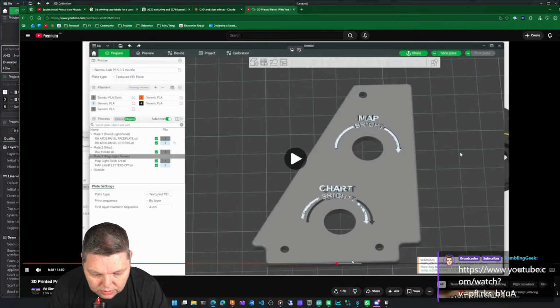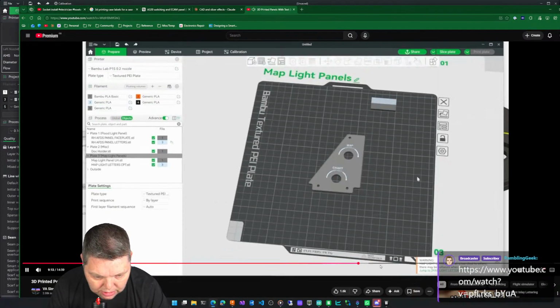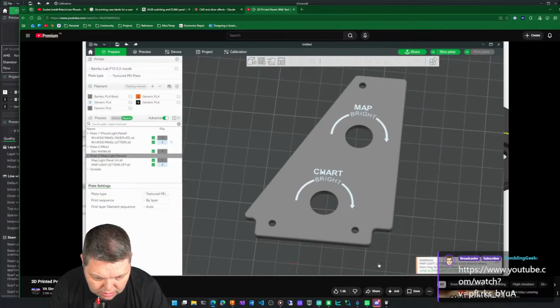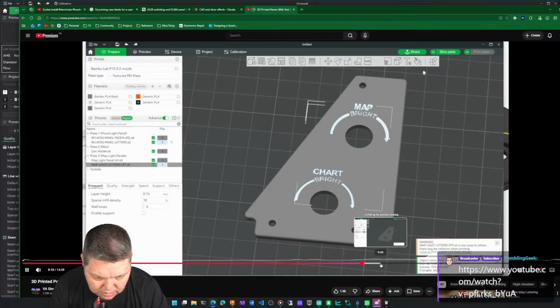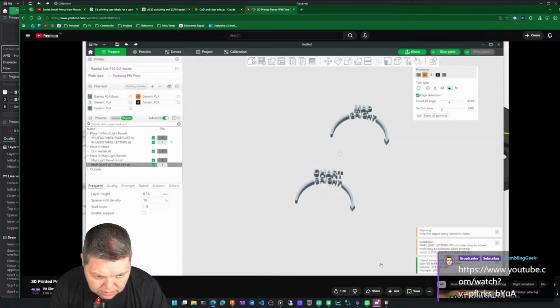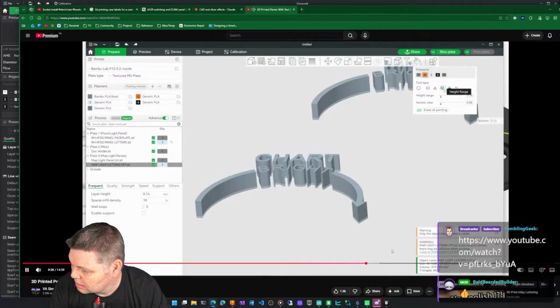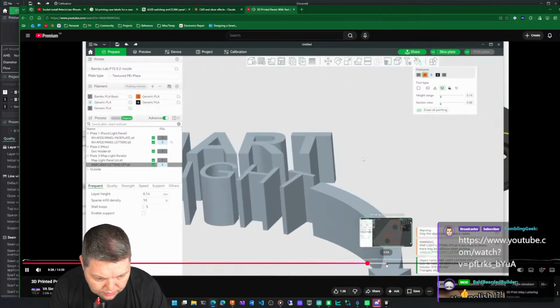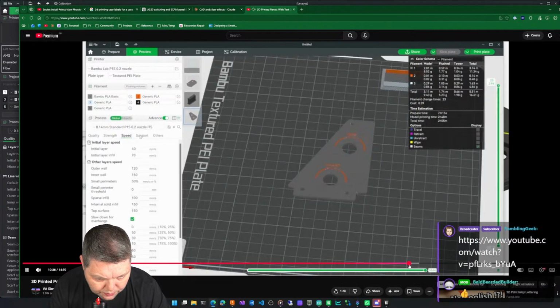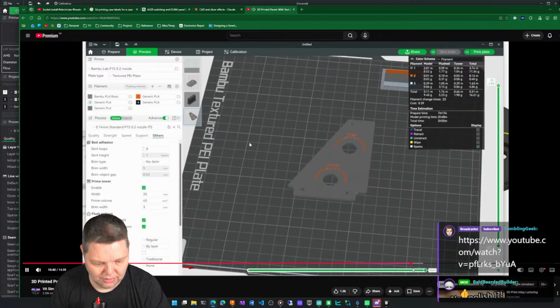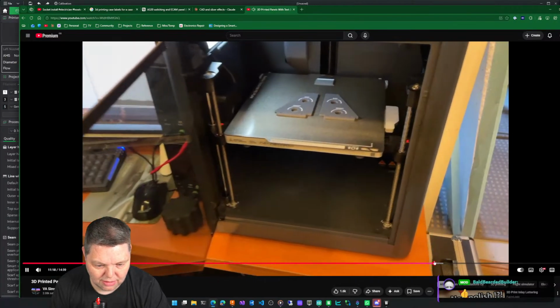So once you've selected them and lined them up, you need to then go ahead and set the top layer to white, and by selecting the paint tool on the Bambu Lab slicer on the top bar, you can go ahead and see the height range. I moved the infill import a little bit weirdly, so it's a little bit messed up, but that's whatever the print was.